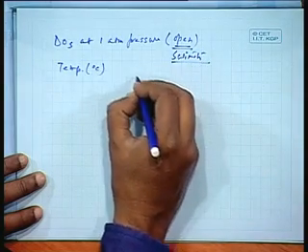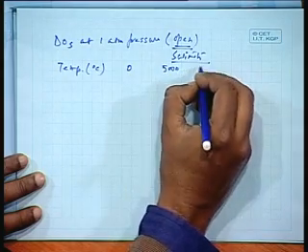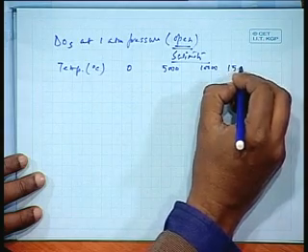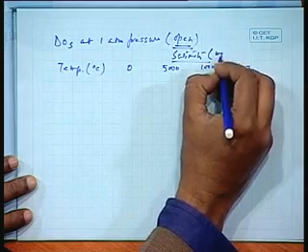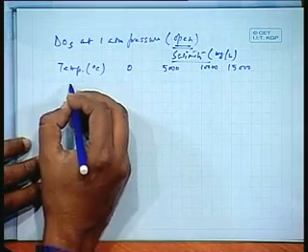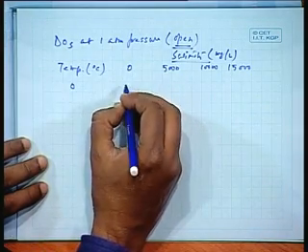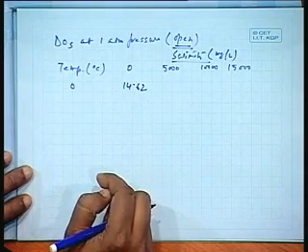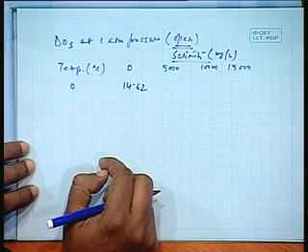The salinity is 0 to 5,000, this is 10,000, and so this salinity is in milligrams per liter. If you just observe this, understandably at 0 degrees centigrade and 0 chloride concentration, we find the maximum value of dissolved oxygen in water, the saturated dissolved value of oxygen. This is the maximum that you can see.